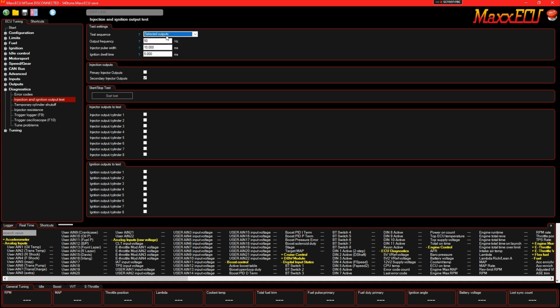So if I was going through, I would put on selected outputs, your frequency, your injector pulse width, your ignition dwell time, and you can go in here and just select each individual one that you want. You'd hit start test. You can test that one, test that one, test that one. And that's for your injectors, and you can go down here and test your coils. Make sure all your coils are clicking. Very nice to make sure, especially whenever you first get your car up and running, make sure everything is actually working.